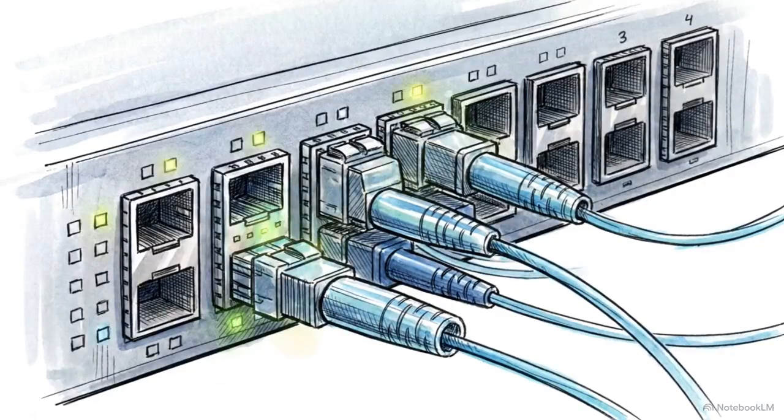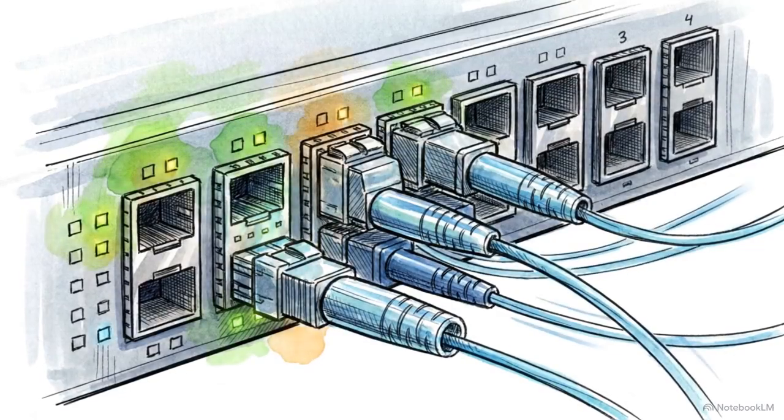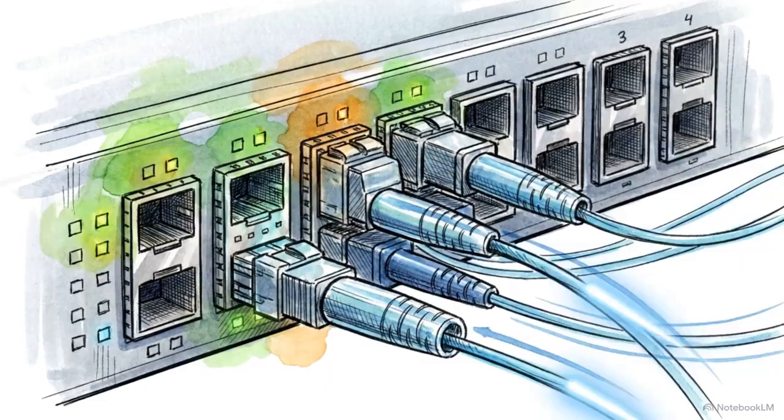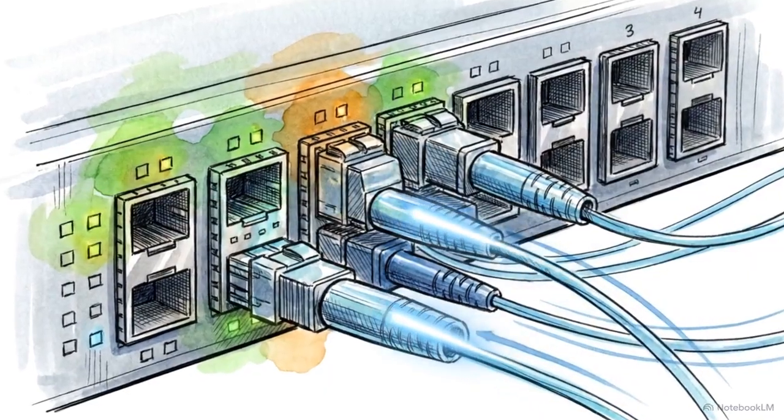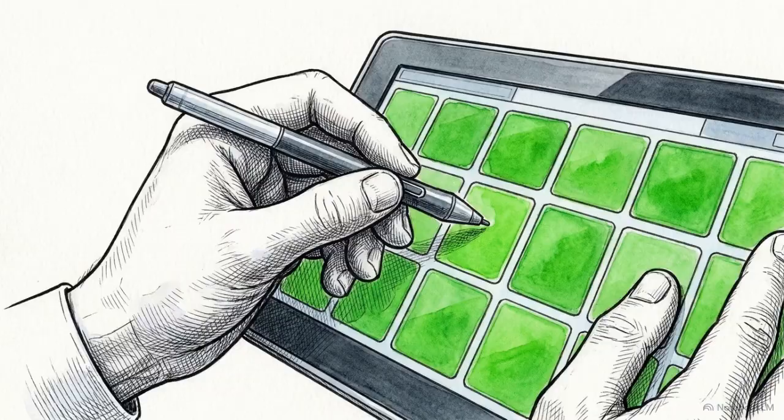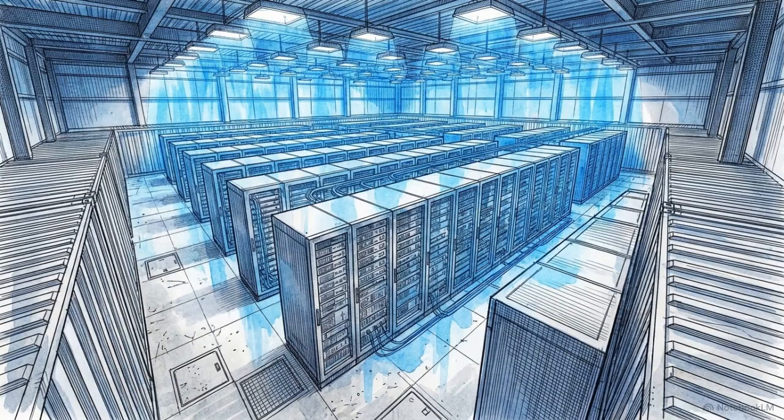Finally, operators close the remaining breakers for sensors and display equipment. This establishes the communication links required for the HMI to receive data from the field. As the HMI boots up, the operator reviews the overview screen to confirm 0 critical alarms, logging this as the baseline normal state. Following this sequential rhythm allows the operator to bring monitoring systems online in a controlled manner, establishing a stable stream of telemetry for the facility.